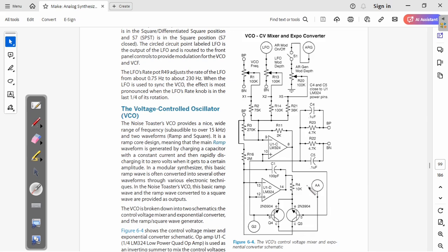So the idea behind all this really is that by changing the voltage here by 18 millivolts, you're going to get a current here. If you add another 18 millivolts to this voltage, so you add 36, this is going to double.